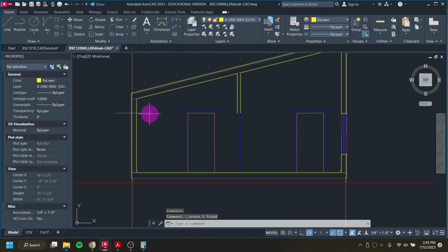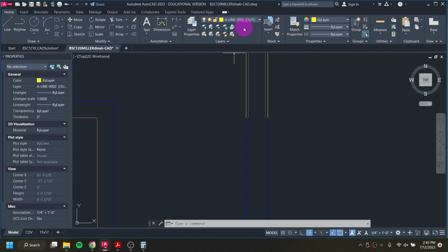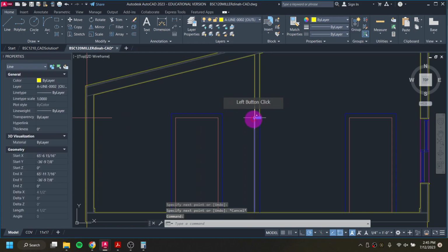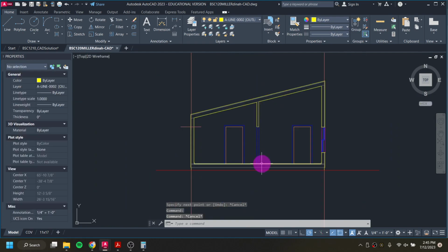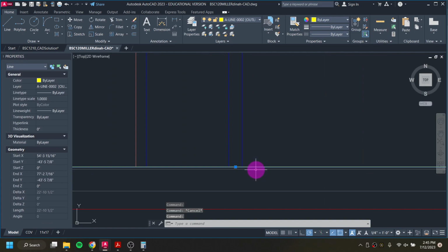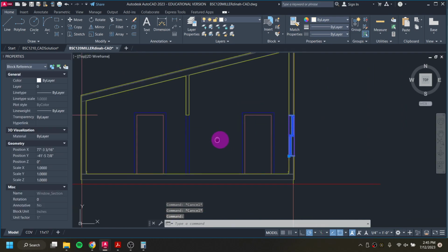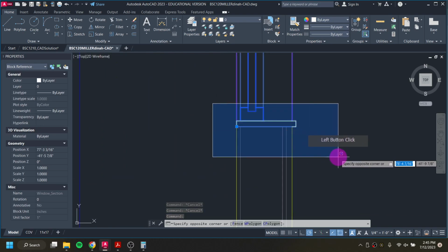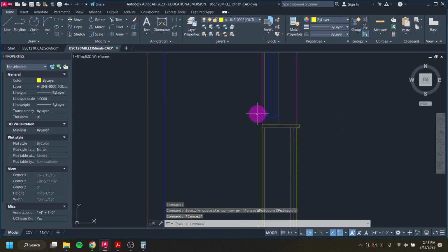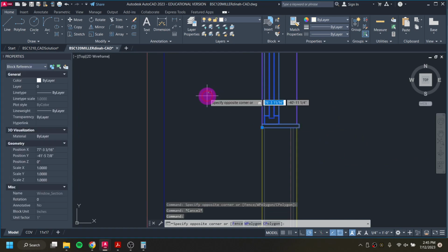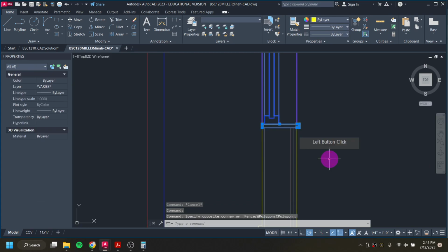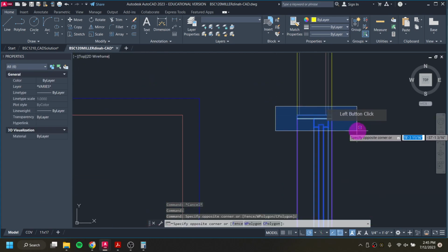Technically, I don't even need my header and stuff on this side because what I'm going to do is a mirror. So I'm going to draw a line just straight across here. Since this is seated perfectly in the middle of my building, I could do it based off that midpoint. I could also have done it based off this line's midpoint, or this line's midpoint. They're all going to be in line with each other. So I'm going to take this window, and this little bit of yellow line work that I made to go with it. I clicked on the window, and then clicked over to the side to move over everything else, and this yellow line work up here too.